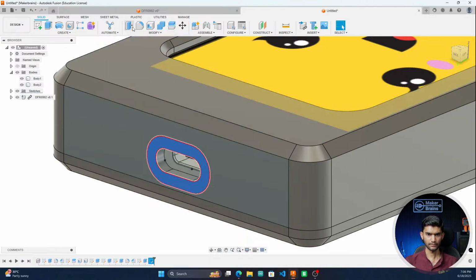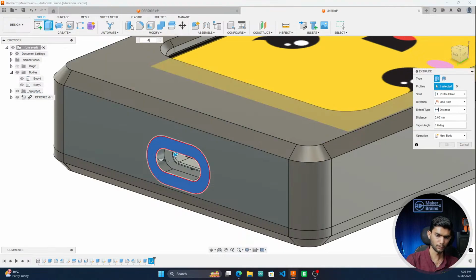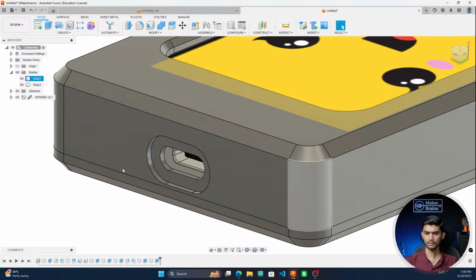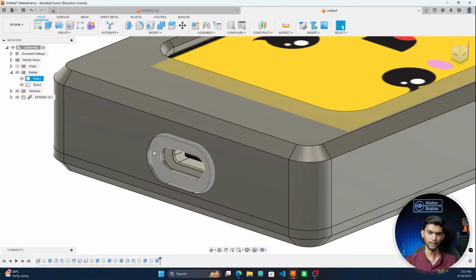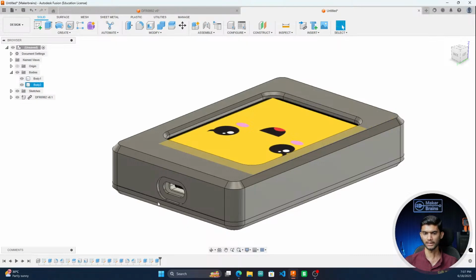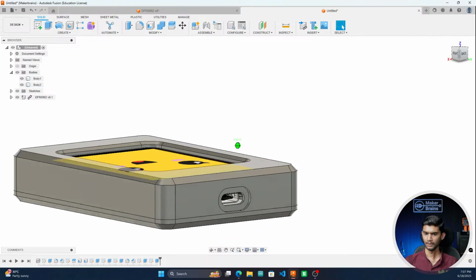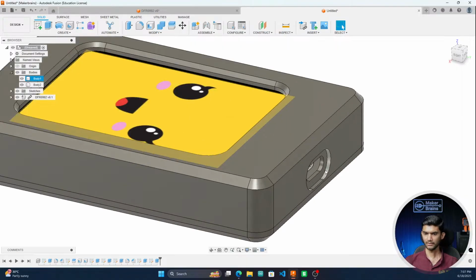And for this I'll set it to minus 1 mm. Why I am doing this is the shape of our USB type C male connector. It can surely go through this hole, but we also have the cable insulation, right? That might interfere while inserting into our product. So I am having this depth as well, so that it can go flush in our device.